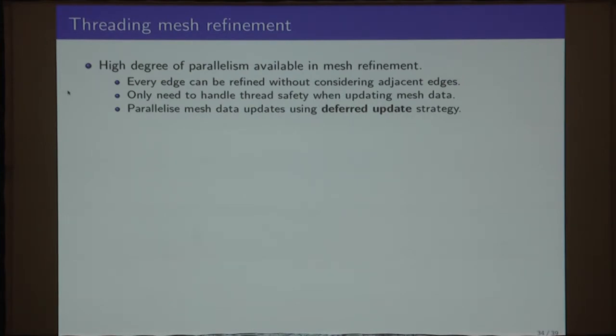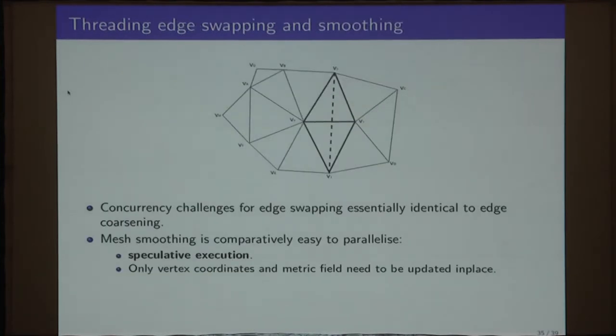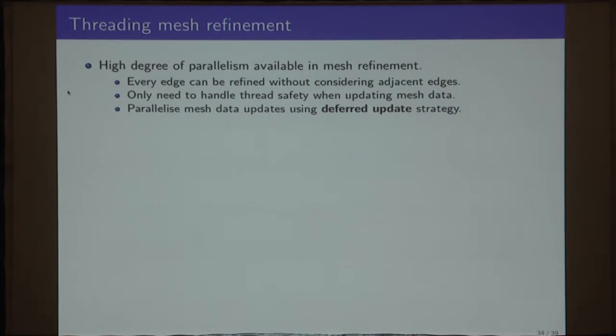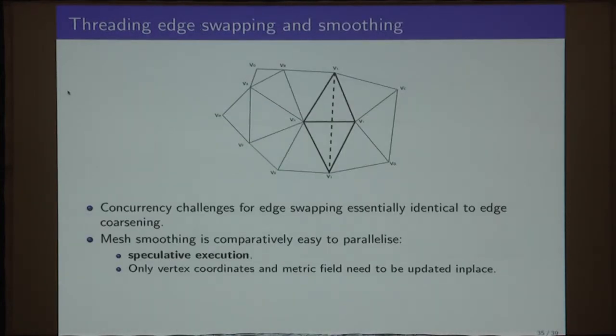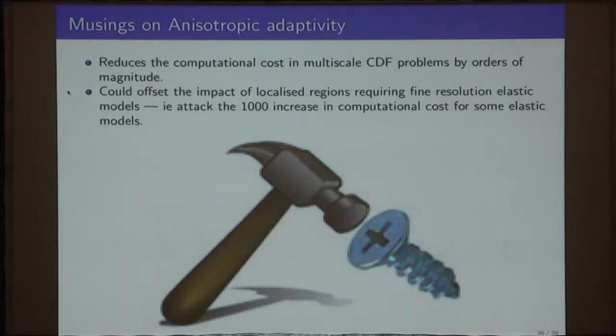Mesh refinement, I don't know what happened to my figure there. But basically that's the opposite. If you identify that actually you need more resolution in this area for whatever reason, then you split the edge. So these are all local operations that are done quite quickly. You can then do swapping of some edges. So this might be very good for aligning with some topographical features or some features inside your model. And it also allows you to generate very elongated elements if the features you're trying to resolve are highly anisotropic.